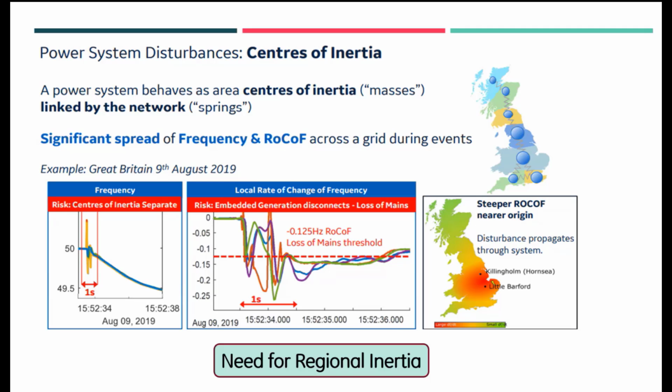But let us say this area has some generation and a weak transmission link, two or three transmission lines, and it can be longitudinal also. This is the case in England or Scotland. There you can utilize the concept of regional inertia. Similarly in India, the Rajasthan pocket has large renewable generation, and other conventional generation has to be shut down, because generation from these power plants is quite high, and there are large RE complexes.